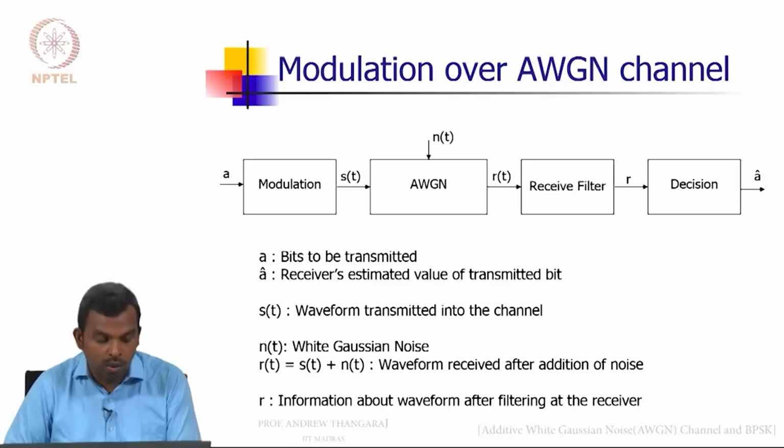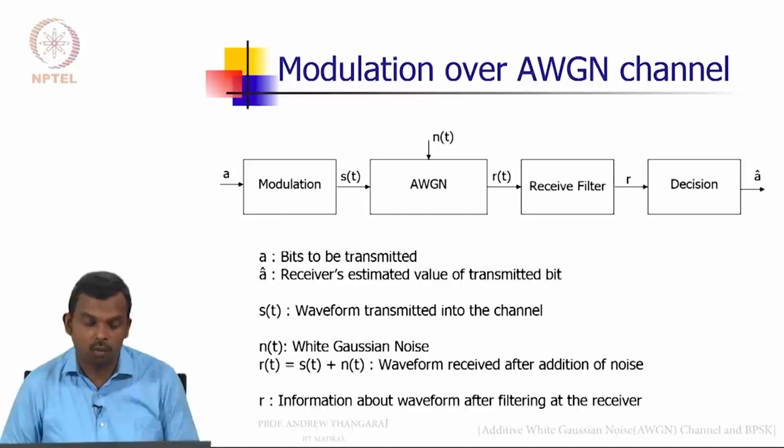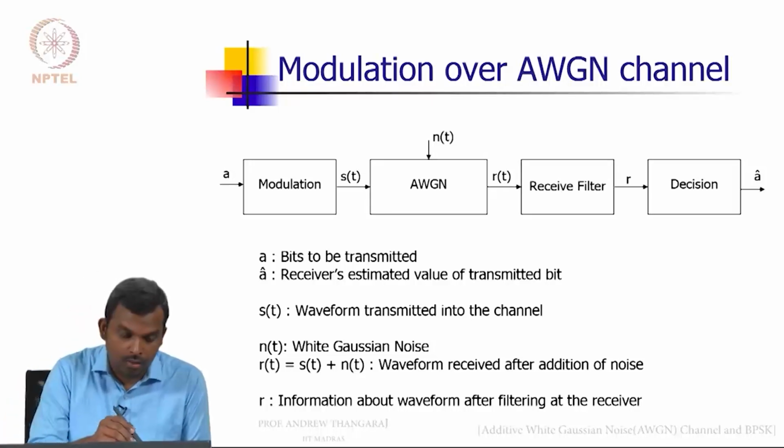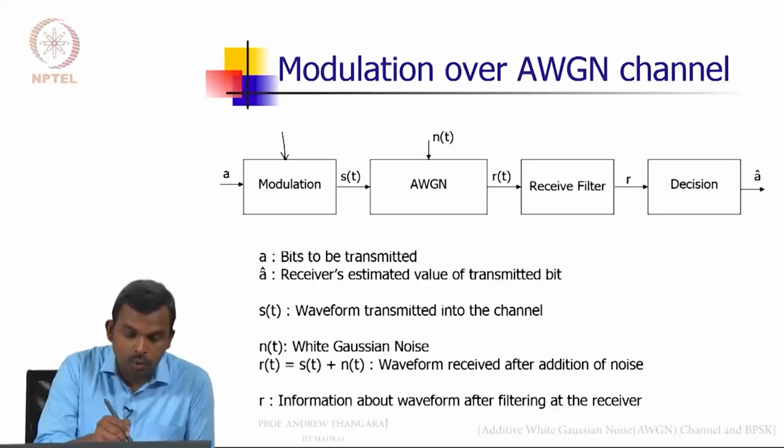As you know, the communication medium will mostly transmit electrical signals, and in a digital communication system, one needs to transmit bits. Bits could be 0 or 1, and how this is done is usually the bits are converted into a signal. That is what is called modulation. That's what is there in the first block here. Modulation refers to converting bits into signals.